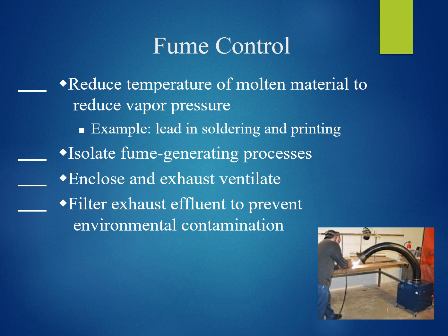Fume control is best accomplished with local exhaust ventilation. Some welding operations can be automated with the use of robotic welders. We see this frequently now in auto manufacturing. This totally isolates the operator from the potential exposure.